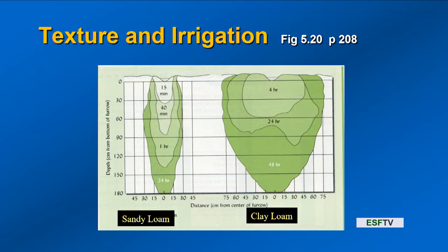And so that's pretty important in terms of irrigation, thinking about where you locate your irrigation furrows and so forth. So an interesting application, and so we tie that back to texture. Texture, one of the important physical properties. We made some generalizations about water movement. Now we can tie that directly to Ksat. We're describing water movement, saturated flow, using this number Ksat. And here we see the impacts of texture. Pretty useful. 15 minutes versus 4 hours. Astounding.